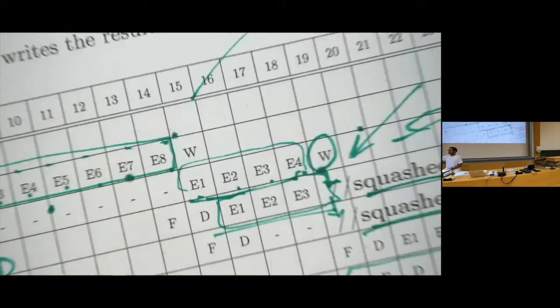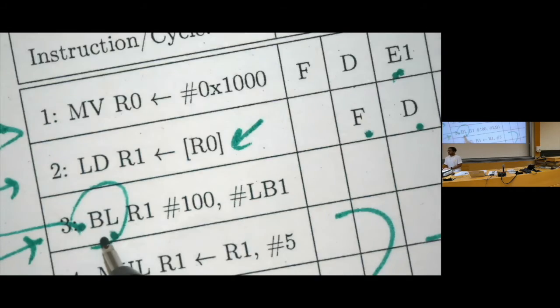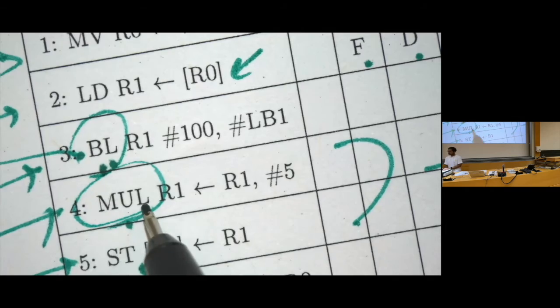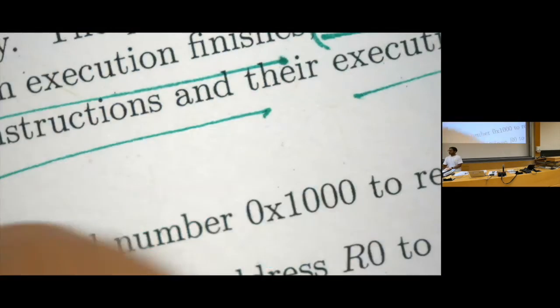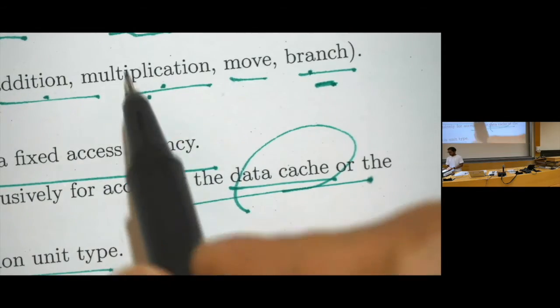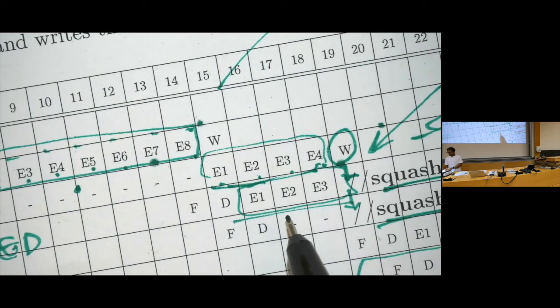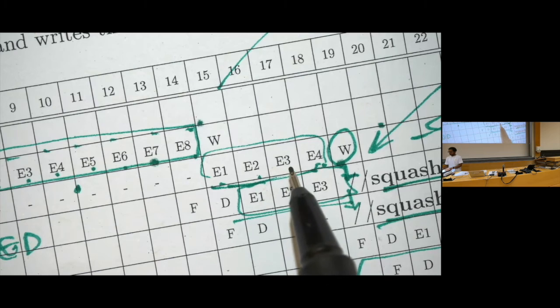Once again, let's zoom into this part. Why do I say it is pipelined? First of all, this is a branch and this is a mul. And I know that the ALU, I apologize for the fast movement, is responsible for executing the branch and the mul. And I see both of them in flight simultaneously at this point. That means, yes, the ALU is indeed pipelined.